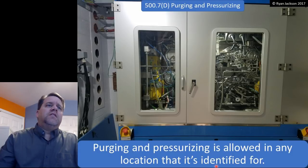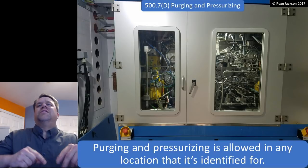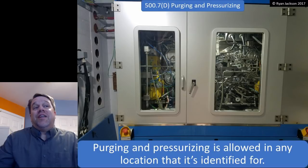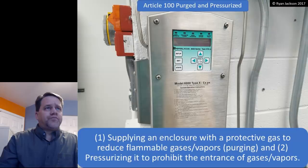Identified is a term that doesn't necessarily mean marked. Identified just means that it's recognizable as being suitable for the application. So in other words, it's designed for that installation. So purging and pressurizing is allowed in any location that it's manufactured for, that it's designed for.